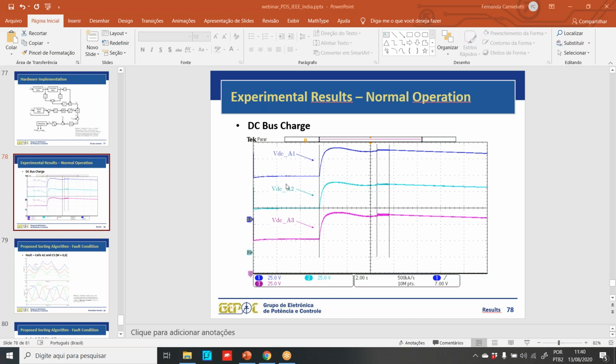Okay. Pre-charging. These are the voltages of the capacitors for the DC bus voltages of phase A. So first of all, we give a pre-charge on the capacitors without controlling the rectifier, just a pre-charge connected to the grid and pre-charged to a given value. And then we keep the inverter open. We don't control the inverter, and we start controlling the rectifiers. So we have a special mode of operation in the central DSP that only controls the rectifier in order for the DC bus voltage to be at the desired value.